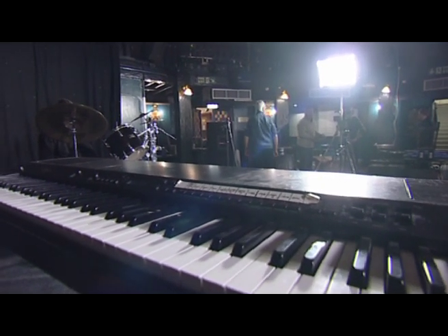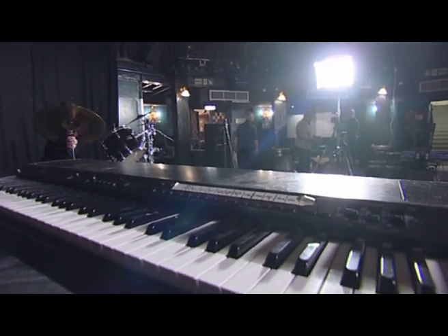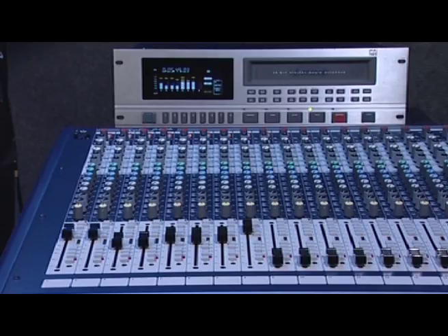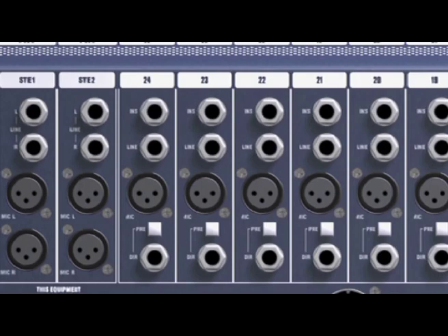Most instruments that you can't hear at all unless you turn them on have line-level outputs, and so do CD and mini-disc players, DAT machines and wireless microphone receivers. Mono outputs can go straight into a mono line input on the mixer. You can plug stereo line sources into the left and right inputs on a stereo channel, or into two adjacent mono channels, as long as you pan them hard right and left.